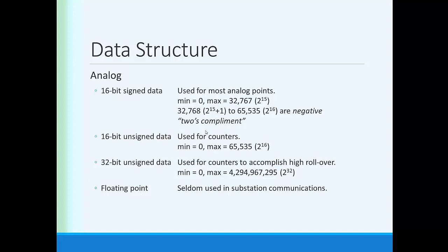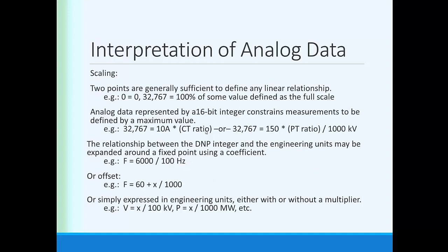Floating point is defined in DNP. It is defined in IEC 61850 and other more advanced protocols. But at the present time, because of the standardization, floating point data is very, very seldom used in the DNP context.